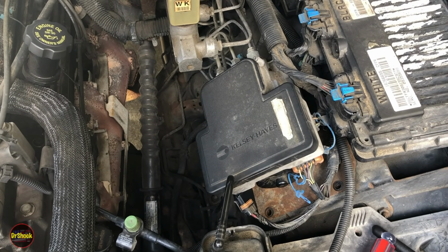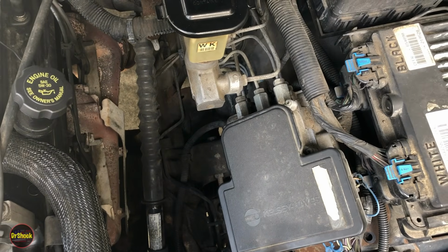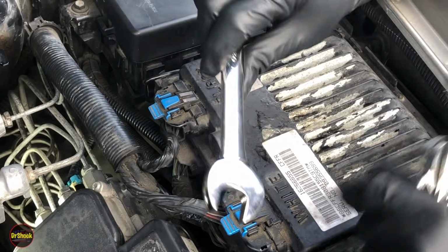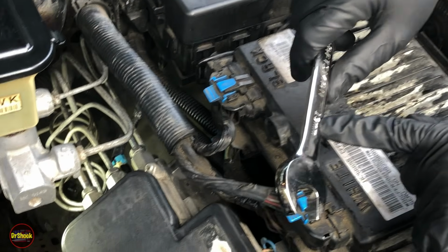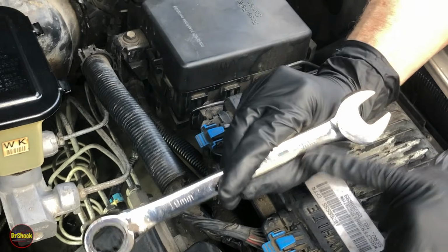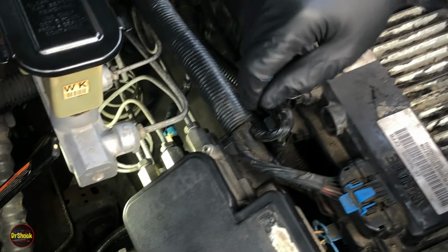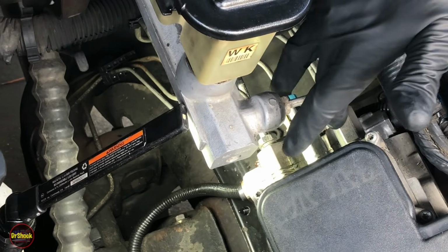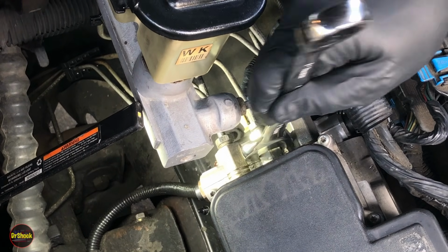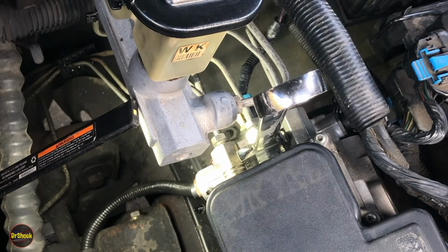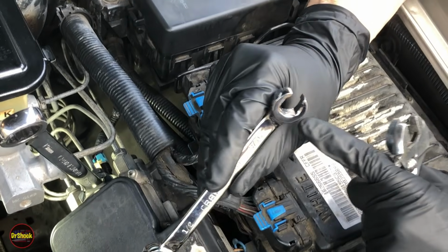We're going to leave the other two in to hold things down until we can release all these fittings. So let's reposition the camera, and we'll come over on this side and take those fittings off. I'm going to go over again the tools that you need for this job when you're getting ready to remove this ABS module. You'll need a 19 millimeter open end wrench, and we're going to use the 19 millimeter wrench to hold these three tubes at the top here. When we get ready to remove these top three brake line fittings, we're going to use the 19 to prevent these guys from coming untorqued. The other tool you're going to need, which is very important, is a 9/16 line wrench.